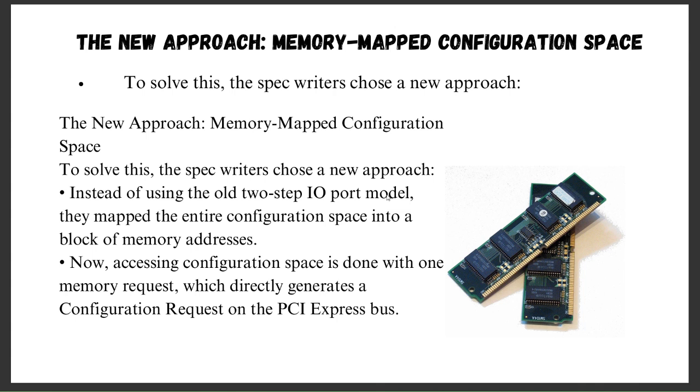To solve this, the writers of the PCI Express specification decided to map the entire PCI configuration space directly into memory addresses. This allows a simpler and faster way of accessing configuration space with a single memory access command. So, memory mapping of configuration space.